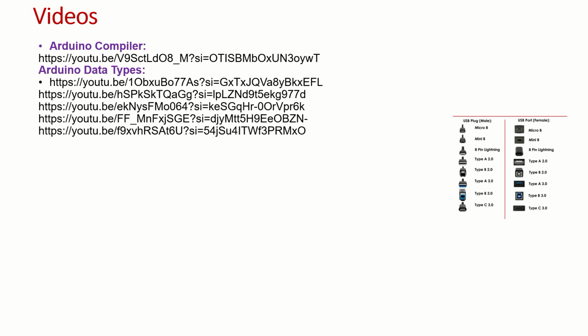For all these programs, do not use any computer-based simulation software. Again, you are making a blunder, because simulations are not 100% foolproof. They only verify the functionality of the programs, not the real-time constraints. So this entire code you verify on the hardware.